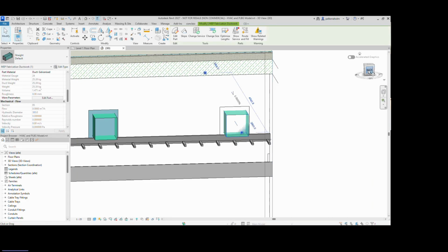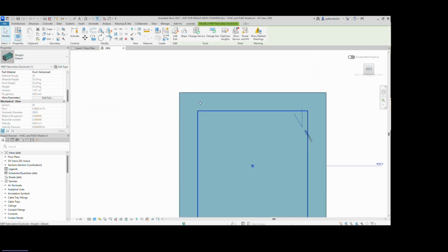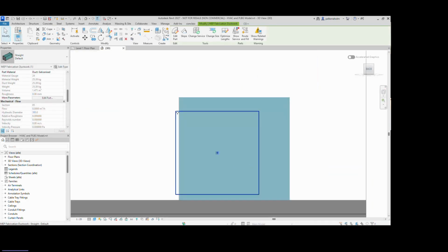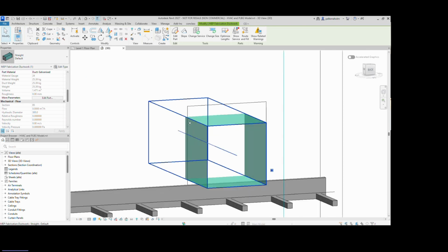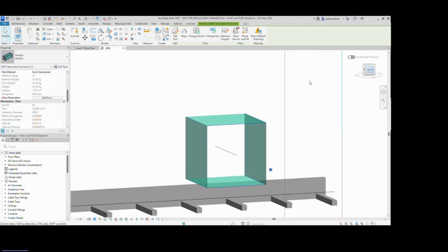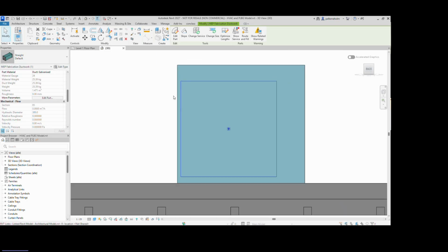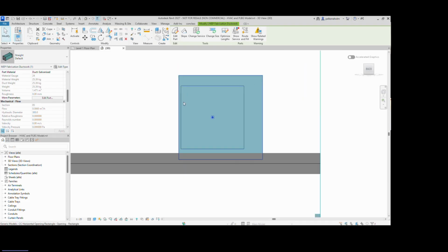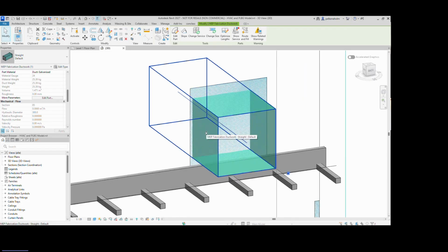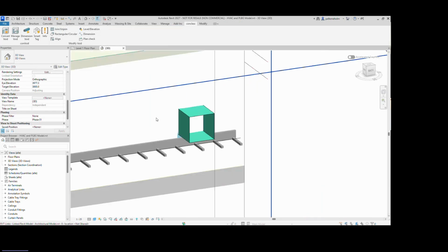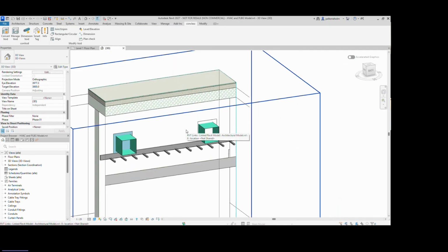and that's it. And it's also working in case an opening or a duct is not completely in an opening. Yeah. So this is also a notification where you detect clashes, or this specific case. Yeah. They might have enough clearance on the right side, but not enough clearance on the left side. So all these clearance zones will be considered. And that's one advantage of using ConVoid.